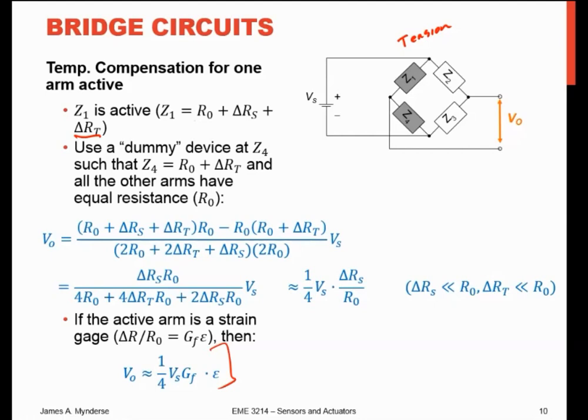Of course, if we're using all 4 strain gauges as strain gauges, you get much the same effect, because the increase in impedance here matches the increase in impedance there, increase in impedance there matches the increase in impedance there, and our balance, the ratio between those, doesn't change much. It does a little bit, but not much, given the fact that delta RT is small compared to R0.